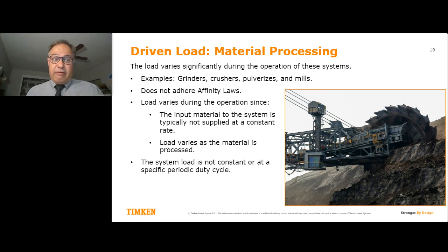This load varies during the operation. There's no fixed duty cycle or periodic pattern, and the input material to the system is typically not supplied at a constant rate, so the load varies as the process continues. So that's another load scenario we want to define and see: would a VFD save me money?